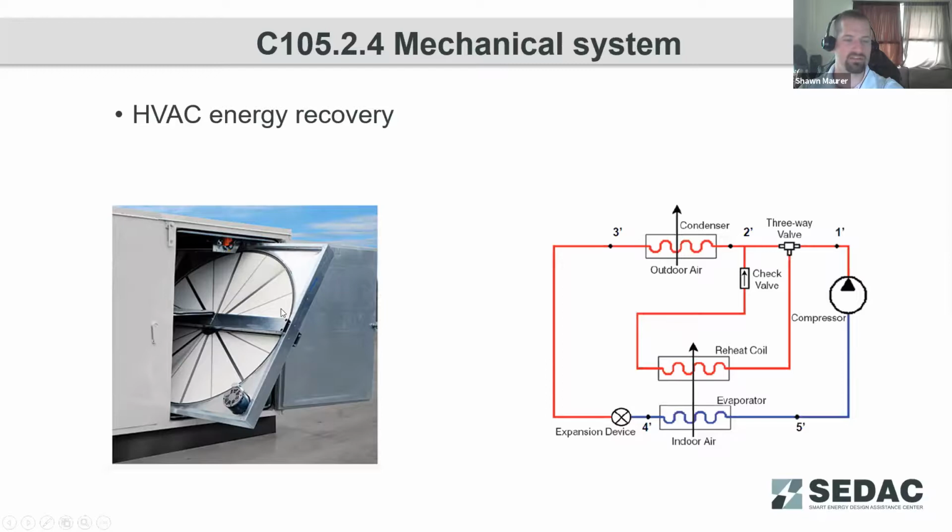Something else to be aware of is that there are certain instances where energy recovery wheels are not allowed, particularly when you've got exhaust fumes that may be hazardous if they were re-entrained into the outdoor fresh air stream. There are other energy recovery options that are available. They're not required by code, but they can save the client a lot of money, particularly now in this age of the COVID pandemic when we're looking to increase outdoor air ventilation rates for buildings as a means to control pathogen spread.